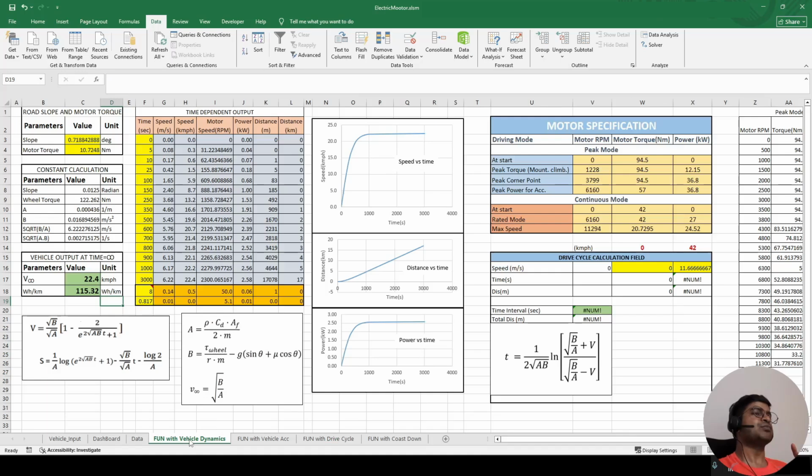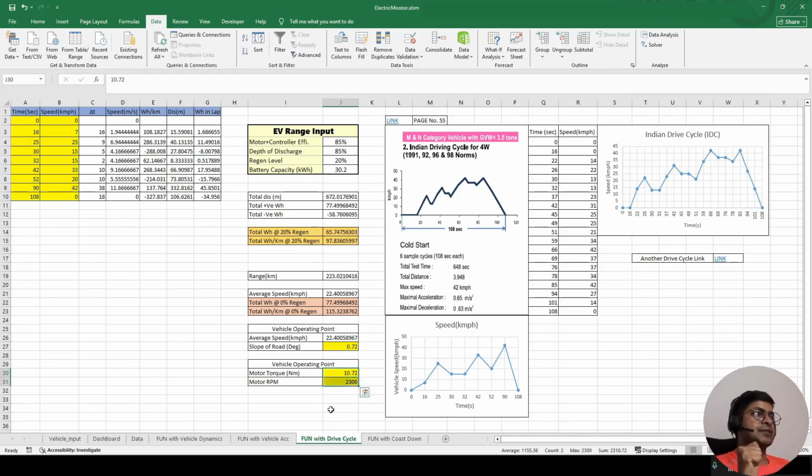And then what is the RPM of the motor at this speed? We got it here, 2300. So that's what I have written. This is the precious pair, because this is where my average efficiency of the motor is going to be. Let's say I am getting the motor from outside, and I will ask the motor manufacturer what is the efficiency at this point, because in my driving cycle this point is going to represent the average efficiency of the motor.